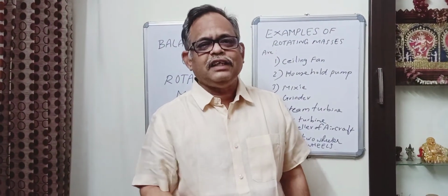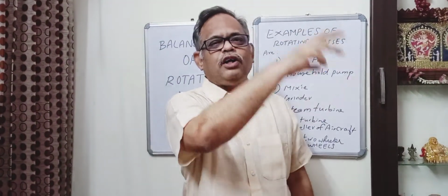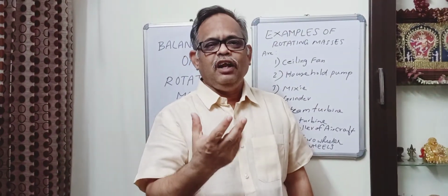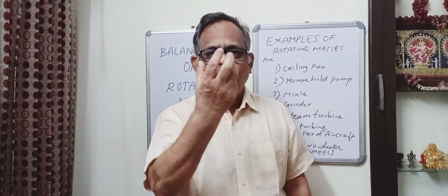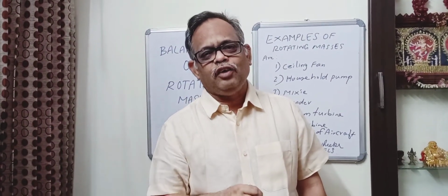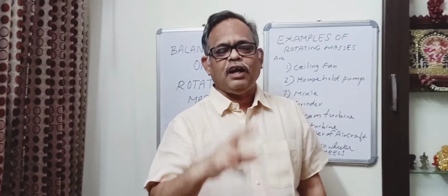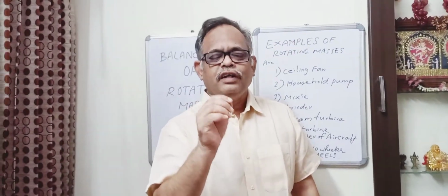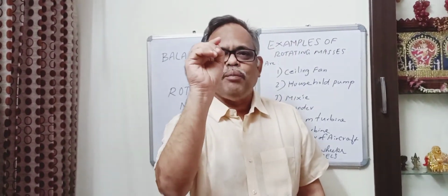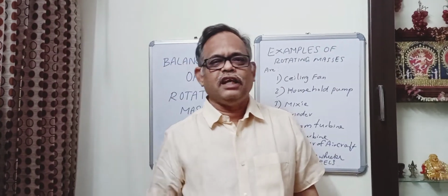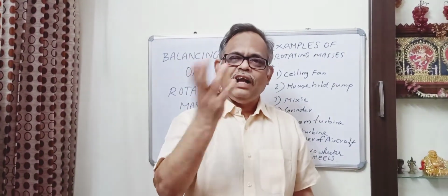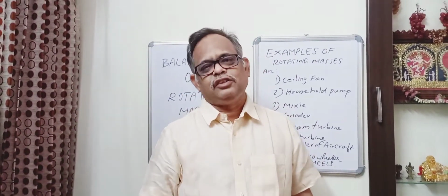So as it does that, the ash particles in the flue gas will pass through the impeller of the fan. When it passes through the impeller, or rotor, of the fan, the ash particles settle at some points on the impeller itself. So this will act as disturbing masses.